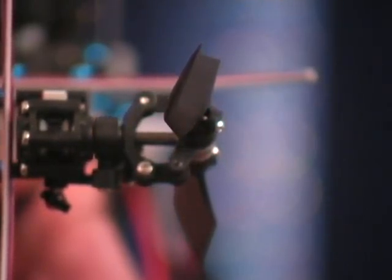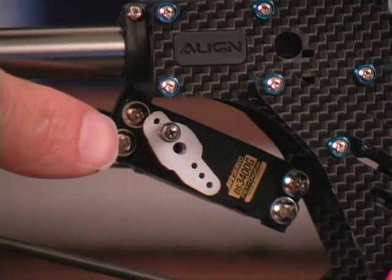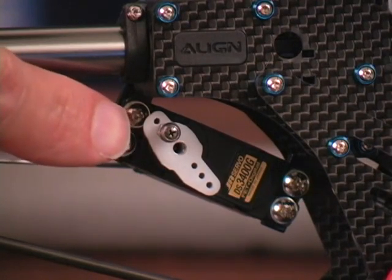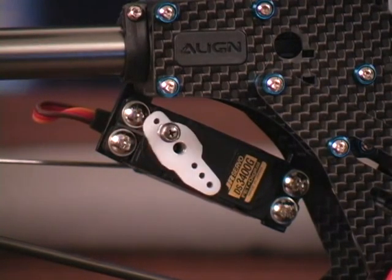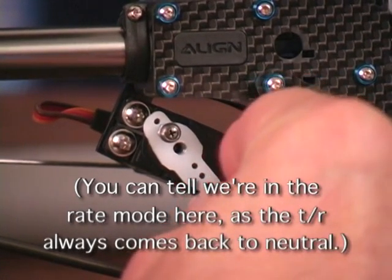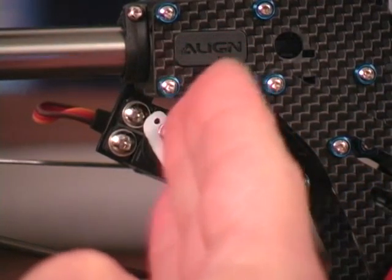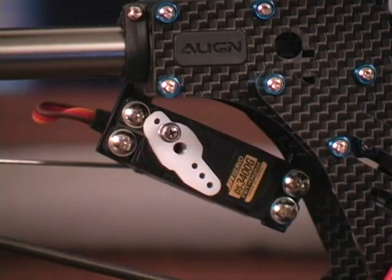Now let's go ahead and move forward to the servo. From my previous shots of trimming the servo arm, I just randomly stuck the tail rotor arm on the servo, and you can see that it's all out of whack. So what I have to do is pull off the tail rotor servo arm and get it as close as I can to perpendicular, 90 degrees. Let me go ahead and do that.